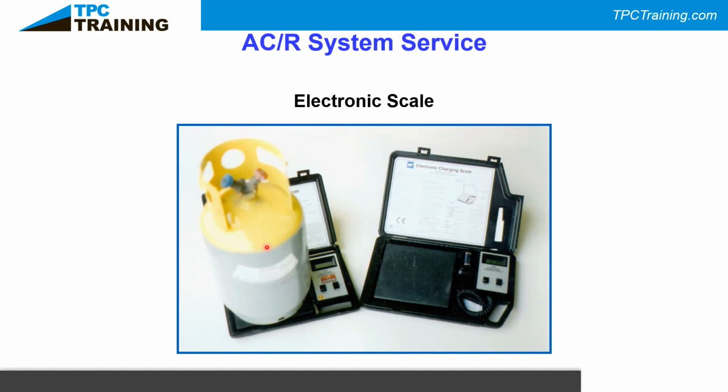It's okay to take the refrigerant out and put it in here and then say, well, apartment 1C is low on refrigerant. I took this out of apartment 1B. It's okay to do that as long as you own the system, own the unit. You're the owner. Once this refrigerant is put in here, the ideal thing we want to do with it is take it and send it back to be reclaimed.